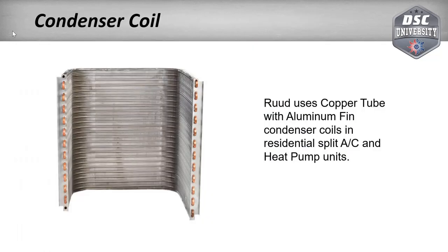So with the scroll compressors, not having the valves was one of the biggest things. Valves used to be usually one of the main failures of compressors back in the day. They would just wear out or break, because they were basically spring steel valves. You ever taken apart a lawnmower engine? Some lawnmower engines use the same kind of valves. They're called reed valves, and they just flap back and forth. Yeah.